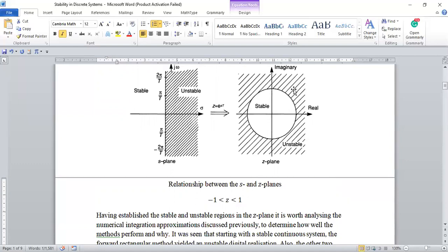If you join them together, you can see that you are outside of the unit circle. That's why we say that it is unstable, because this is 1 here. So 0.8 will be towards the end, then 0.8 on the imaginary axis is towards this place. When you join it together, the point you have here is outside of the unit circle, so it's unstable.